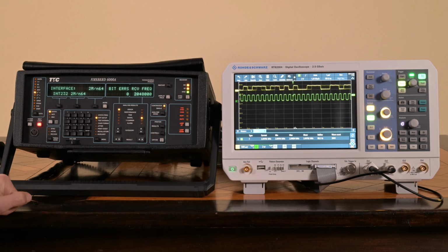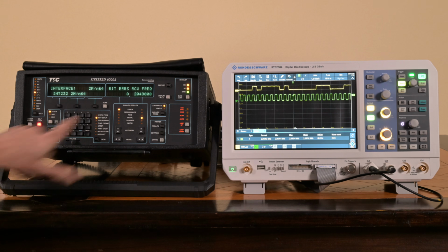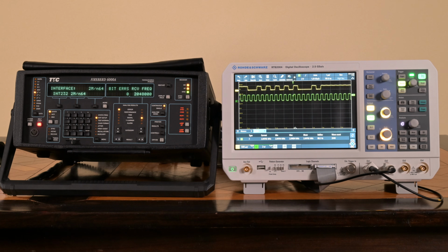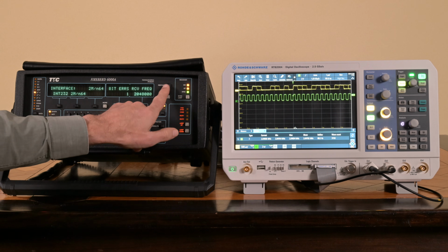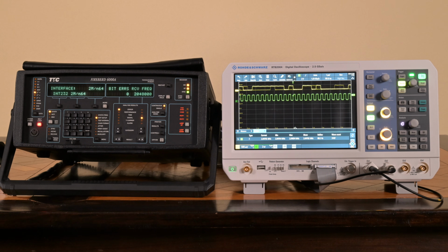So now we're running an E1 interface with the device itself in its self loop. I see the frequency I'm expecting, that is 2048 kilohertz, so about 2 megahertz here, and the unit is reporting no error. I can insert a manual error and then we get to see a manual error, and I can press restart and then it resets all the analysis findings.